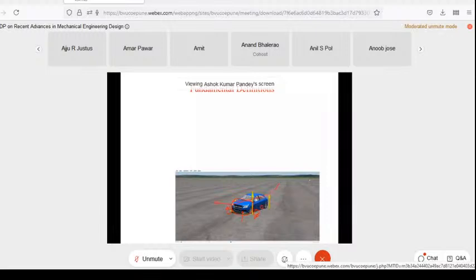So when it turns, you will see that this portion will try to move like this, and the whole load will get transferred to this portion of the vehicle, and this portion will have less load, because the tire contact will lift. This side will lift, and this side will go back down. So the normal loads of the outer portion of your car will increase as compared to that over here.